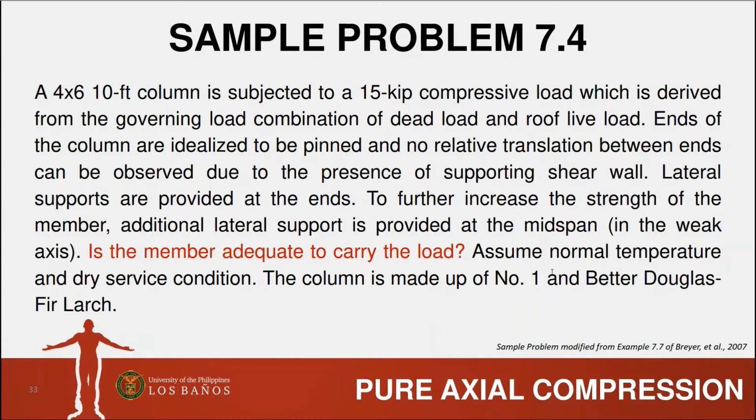Lateral supports are provided at the ends, and to further increase the strength of the member, additional lateral support is provided at the midspan on the weak axis. So is the member adequate to carry the load? Assume normal temperature and dry service condition. The column is made of number 1 and better Douglas fir larch.